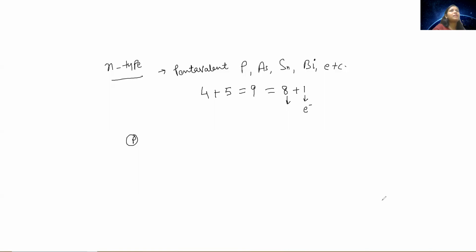Hello students, this is the next video in continuation to the previous video. I told you the p-type semiconductor material. Let me tell you now the n-type semiconductor materials. In n-type, I told you previously that we use pentavalent elements along with the pure semiconductor. These pentavalent elements are such as phosphorus, arsenic, antimony, bismuth. I'm taking an example of phosphorus element.